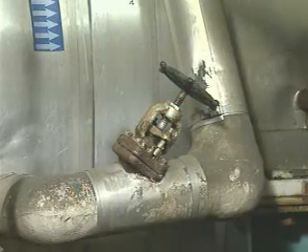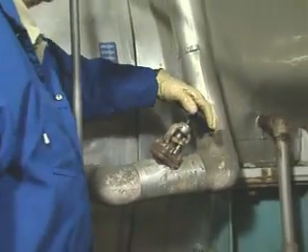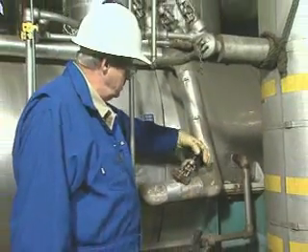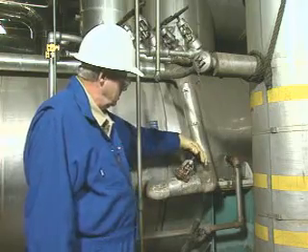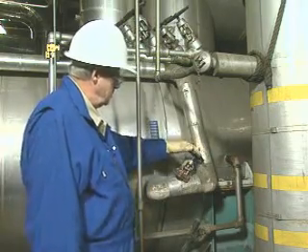You can usually correct the problem of air binding on the shell side of a heater by venting the shell side to remove the air. The TTD should then return to normal.